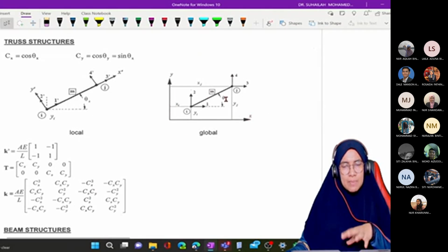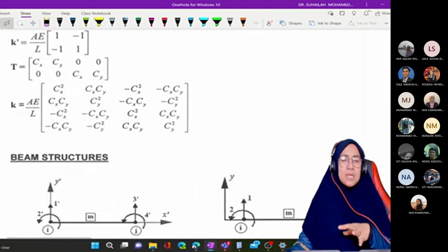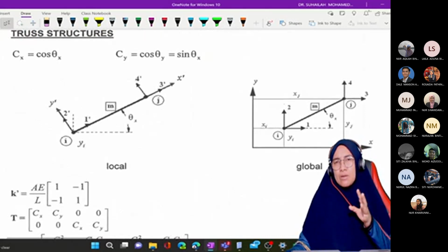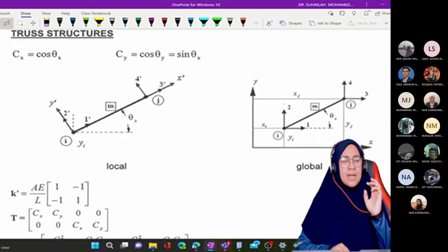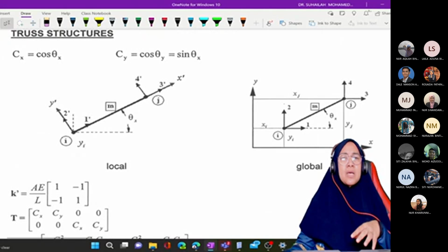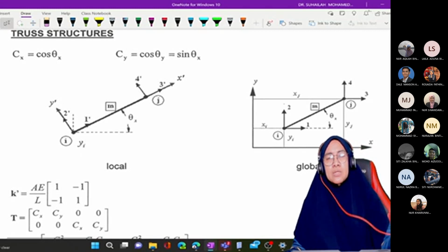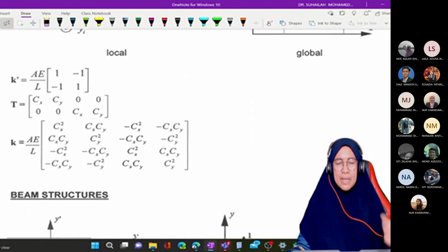That is why we get negative and positive signs like this. So do not change the sign convention. Every semester some people change it, and if you change it, you will definitely fail. You cannot change the sign convention because it relates to the formula we use to calculate element stiffness matrices.